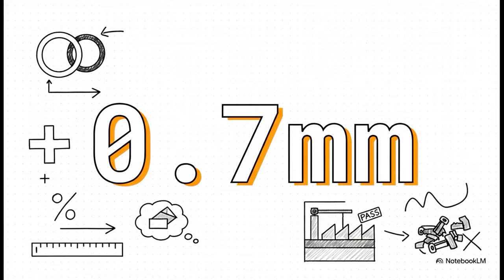By simply drilling the hole slightly larger than the absolute minimum, the manufacturer just gained a massive 40% increase in their positional tolerance. Honestly, that is often the difference between throwing a really expensive part straight into the scrap bin and legally passing it for functional assembly. This right here is exactly why manufacturers absolutely love the MMC modifier.